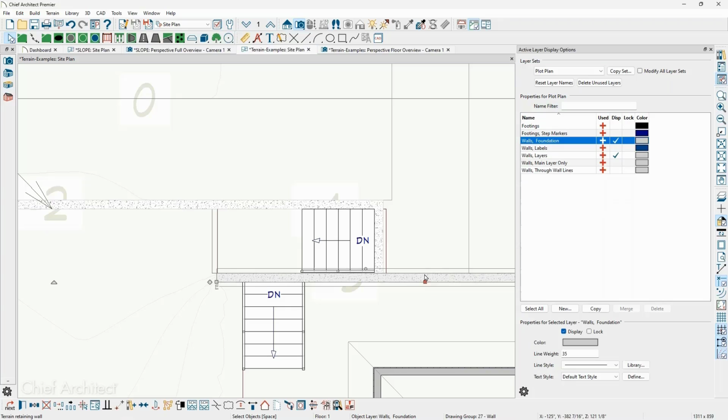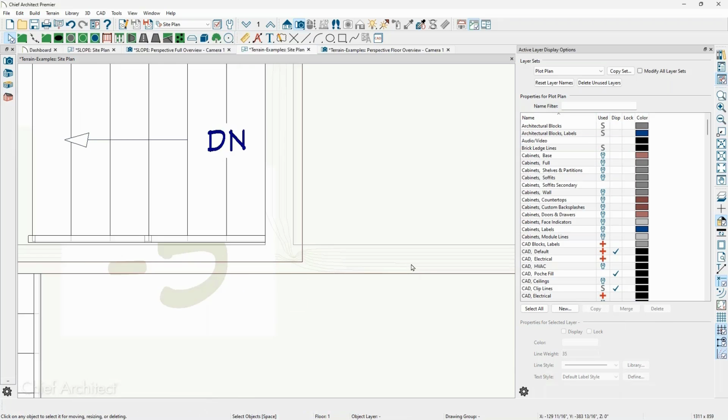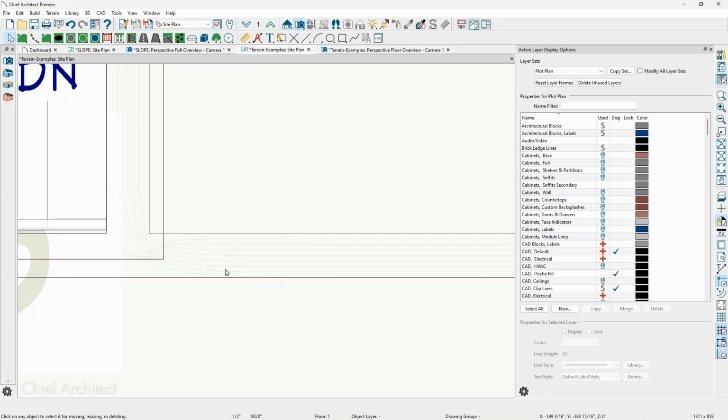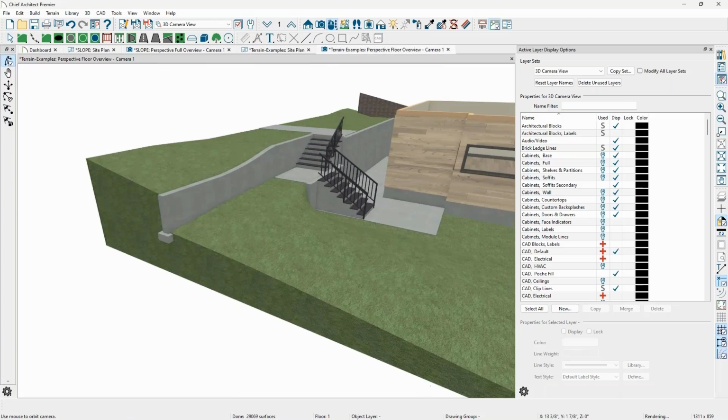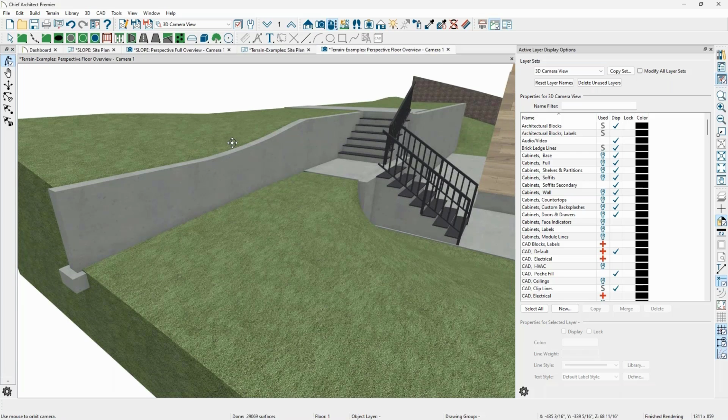It can be helpful if I just take this wall and turn off the layers. Sometimes it's nice because then you can see where the contours actually are. It's probably really tough to see on your screen, but you can zoom in and see where those contours are, and that way you can figure out if that's working for you. I try to avoid relying on the terrain wall or the retaining wall because it can follow the slope. If I zoom out a little bit, you can see how it's following that slope. I like to draw those myself. You can take an elevation view and square it up, but I like to do that myself and use the terrain regions. Then I can see where the contours are exactly. Then I'll draw my wall and dimension it, and I know those walls will not be interacting with the terrain itself. Perfect. Great. Thank you very much.